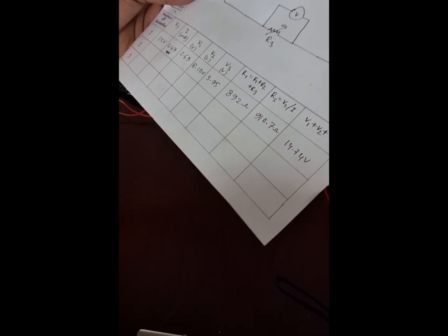So we can see that we are very close to the measurement, and we see that the voltage we supplied is 15 volts and what we measured across each rheostat sums to 14.74 volts. So that is also very close. We can say that there are always some losses and we will not get the exact value, and we can accept the close values. Hence our verification of KVL is proven.